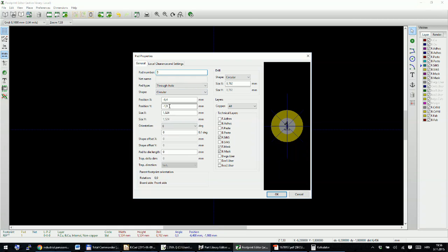I will edit it. So position, let's say for the timing I'll put this at 0. This will be also at 0, and we need to have beefy wire. Let's say at least 2mm wire. So let's make this 4mm. And hole, let's make 2mm hole. So this is drill hole in a PCB, and let's make this rectangular. Yeah, rectangular, and I will make 4 by 4mm just to be bigger. Yeah, okay. This is good enough.